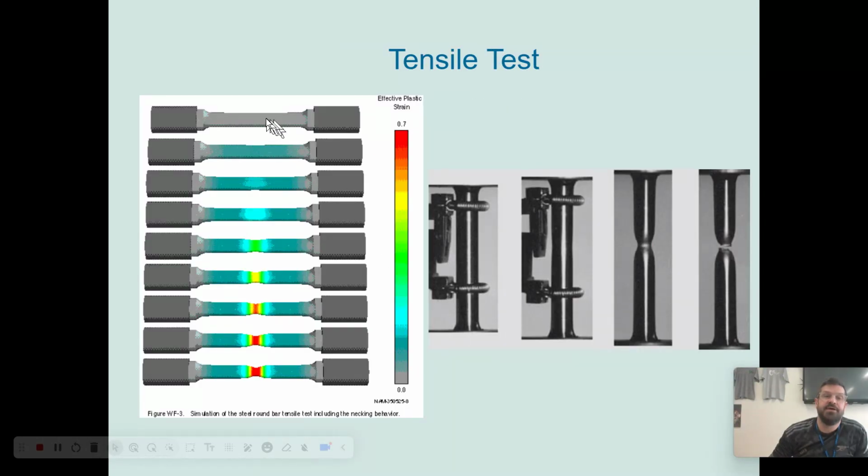Okay? So if you look at it like this, this is what it looks like. It starts off kind of like normal before any load. It stretches uniformly. You can see maybe here at the beginning, there's just the tiniest little hint of a neck. This is what a neck looks like because the material is getting skinnier at that one part. At that moment, all of the force that you're pulling up and pulling down gets concentrated right there, and then eventually it just breaks.